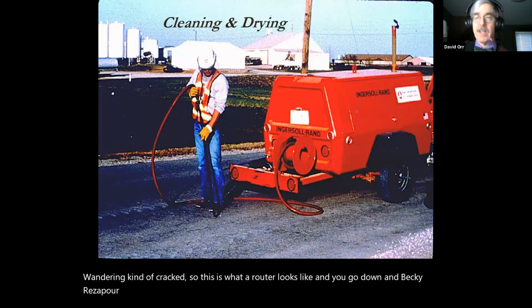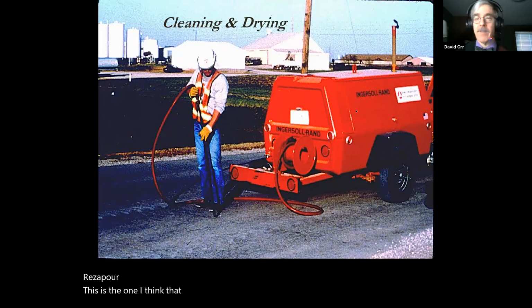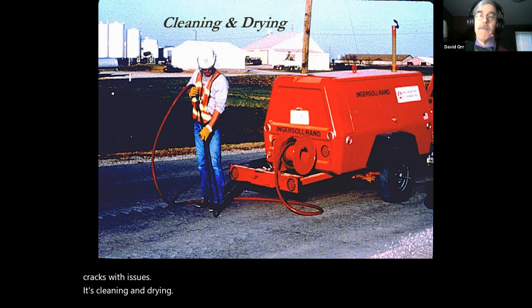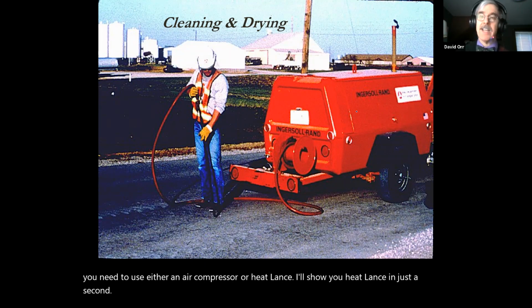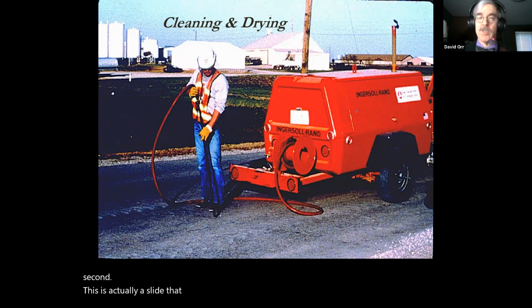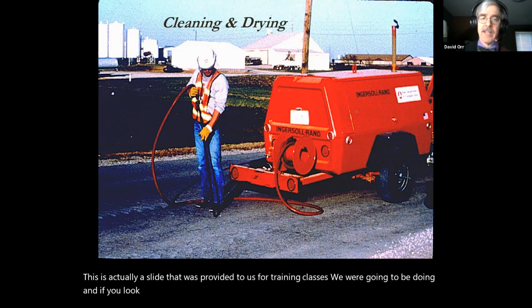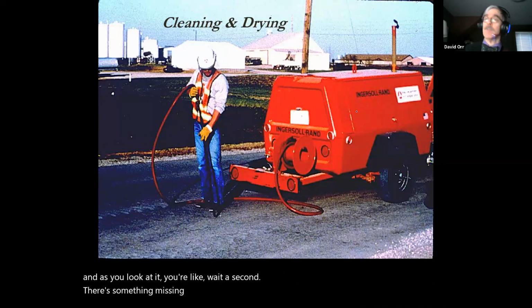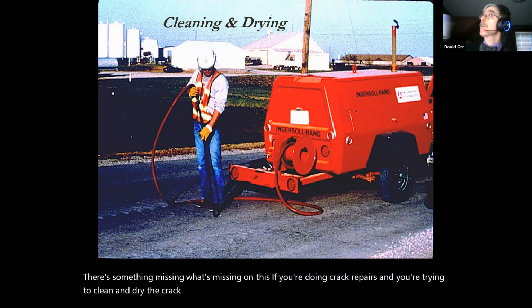This is the one I think that I see the biggest problems when I've gone around and looked at cracks with issues. It's cleaning and drying. To clean and dry, you need to use either an air compressor or heat lamps. I'll show you heat lamps in just a second. This is actually a slide that was provided to us for training classes we were going to be doing. And as you look at it, you're like, wait a second, there's something missing. What's missing on this if you're doing crack repairs and you're trying to clean and dry the crack? What's missing here? Throw it in the Q&A pod for me.